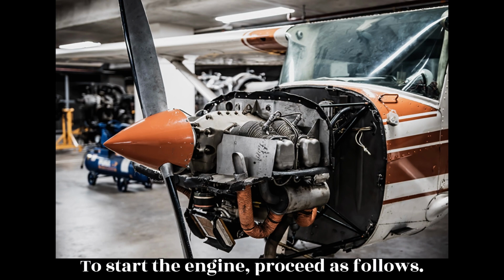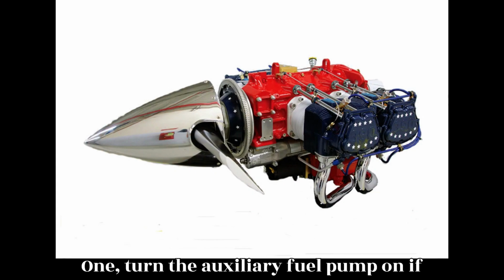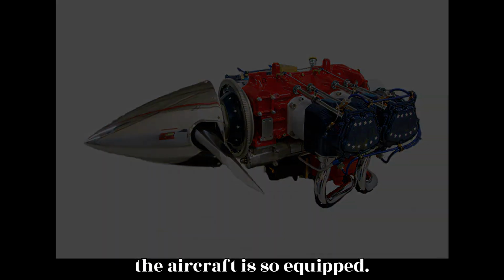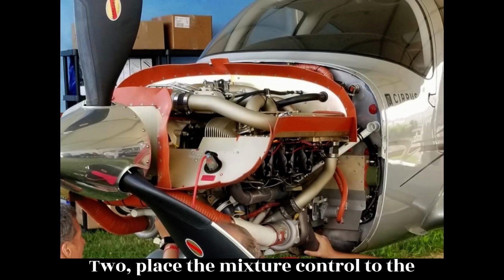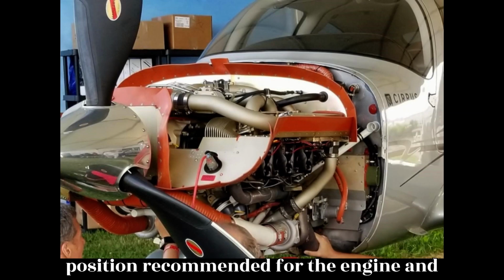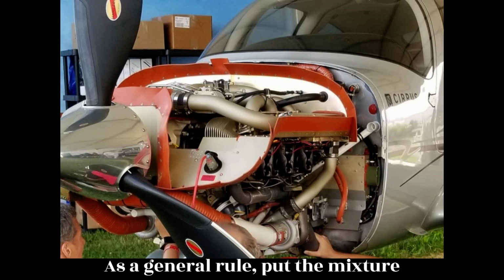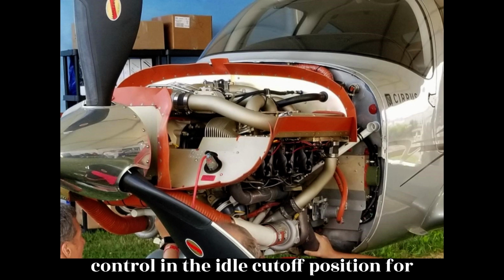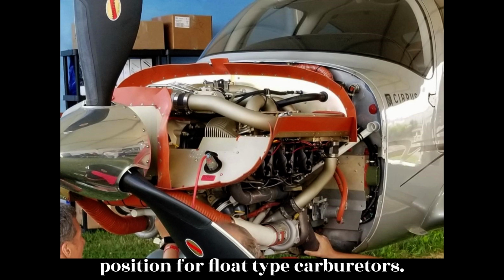To start the engine, proceed as follows. 1. Turn the auxiliary fuel pump on, if the aircraft is so equipped. 2. Place the mixture control to the position recommended for the engine and carburetor combination being started. As a general rule, put the mixture control in the idle cutoff position for fuel injection and in the full rich position for float-type carburetors.